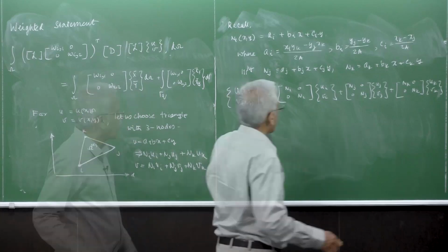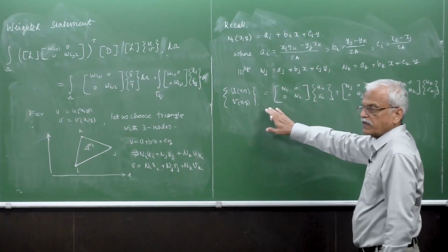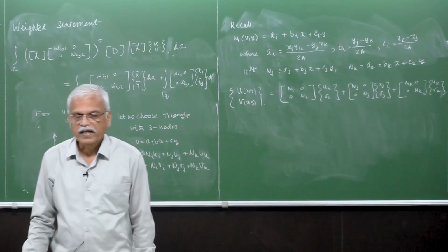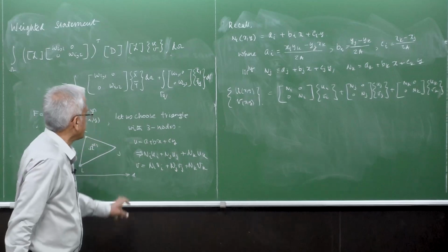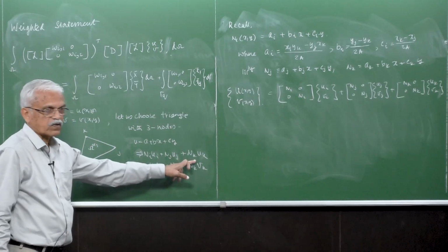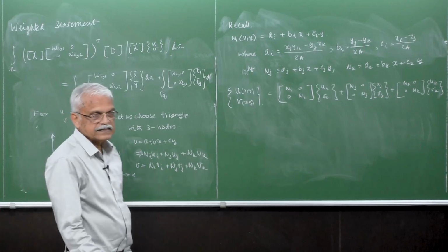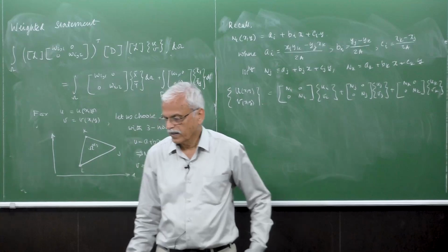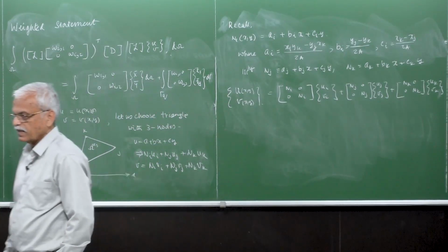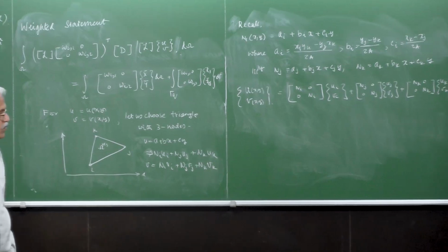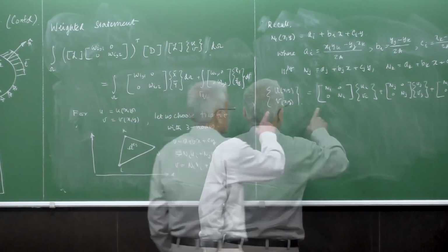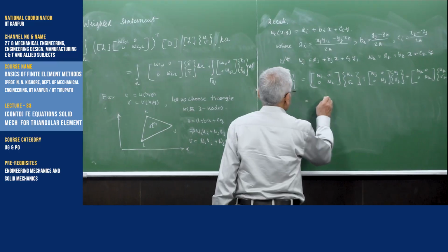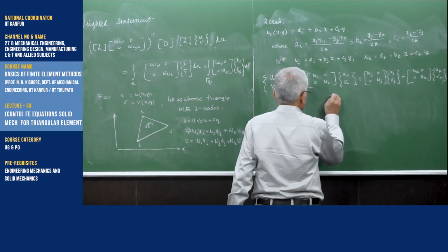So this is how u, v varies within the element, and since these are expressed in terms of N and the nodal values, obviously the C0 continuity is also guaranteed. So this now satisfies all the conditions of integration, and in the matrix form it's expressed like this one.